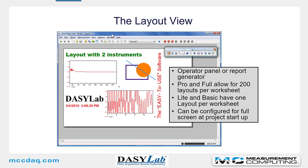DASYLab's layout view is accessed from the Window menu or by clicking on the Layout shortcut button. The layout view is an operator panel or a report panel. DASYLab Pro and Full allow for up to 200 layouts per worksheet. DASYLab Lite and Basic have 1 layout per worksheet. Layouts can be configured for full screen at project startup. With DASYLab 2020, you also have the ability to display layouts on more than one monitor and to control which monitor a layout is displayed on.